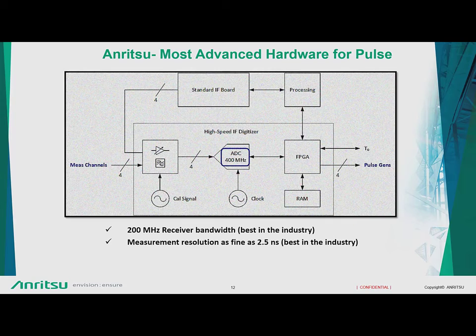So even a small ringing or an overshoot which exceeds the power handling capacity of, say, an amplifier or a filter of a subsystem can destroy the entire system. So that's why you need to very finely resolve these pulses. That's why higher and higher resolution is basically required.